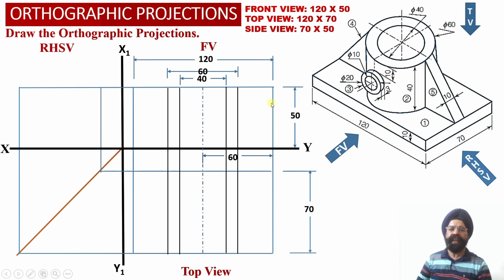So this way we have been able to locate internal diameter endpoints and external diameter endpoints corresponding to this vertical hollow cylinder, which is our element number 2. Now we also know that corresponding to this cylindrical element over here, which is going to carry a snug, which is going to have a screw over here, so that we can secure the shaft within this hollow cylinder.